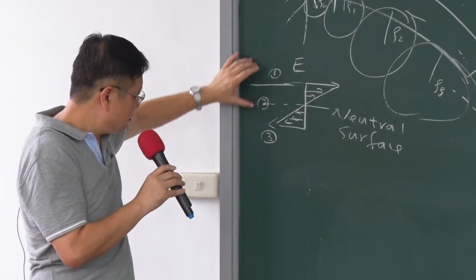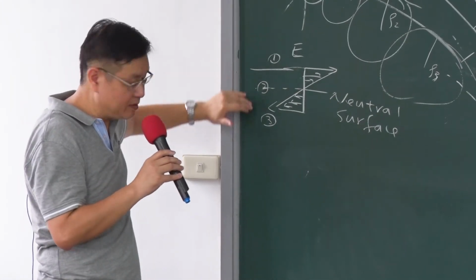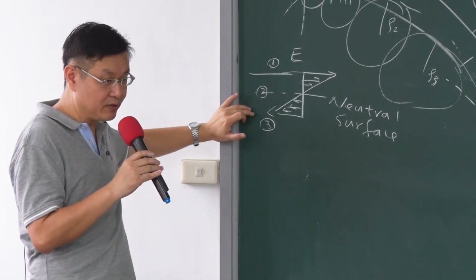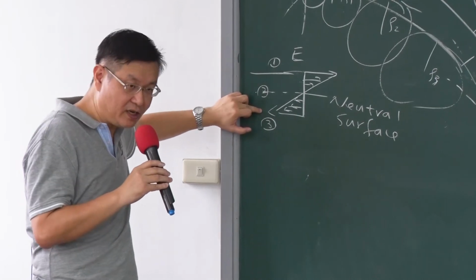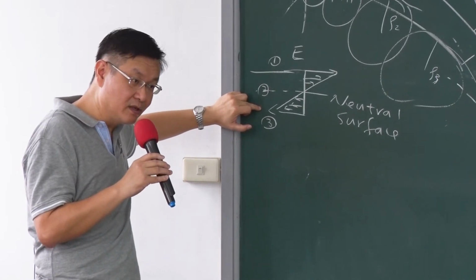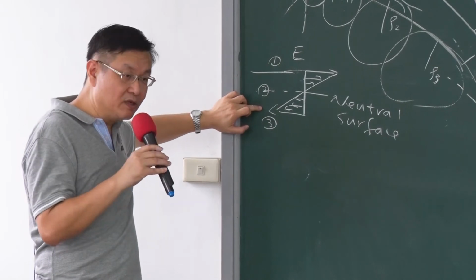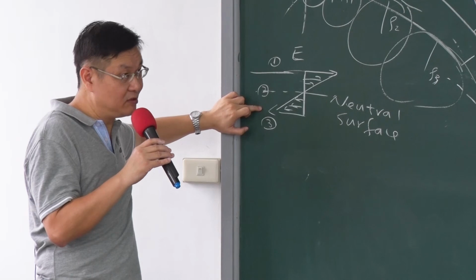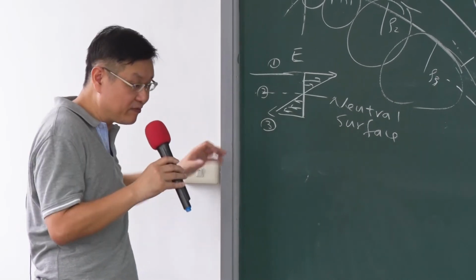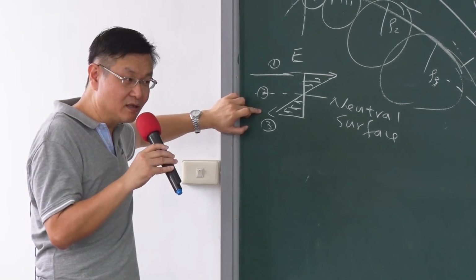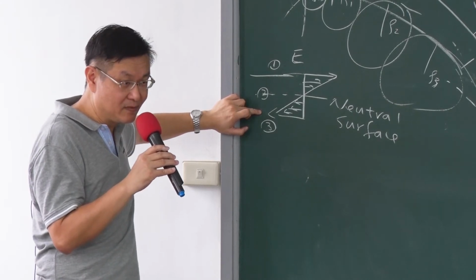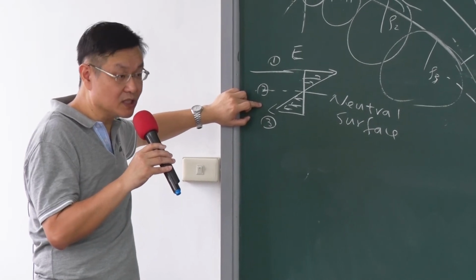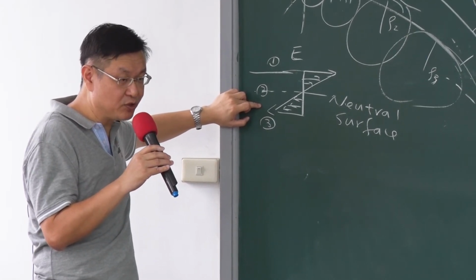So when you do the squeeze, now we consider here, we have two positions. You can put the sensor on the top or on the bottom, right? On the top you have extension. On the bottom you have a squeeze, compression. So if we put the n-type piezoresistor here, when we do the squeeze, it will give you positive results. So the resistance will increase when you squeeze the n-type film on the bottom. But if you put the p-type here, the resistance will decrease. Okay, they will have opposite signs.